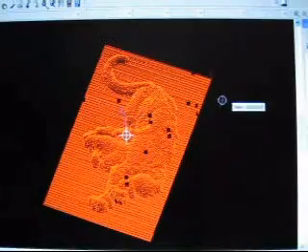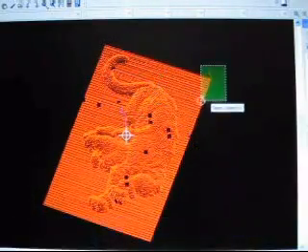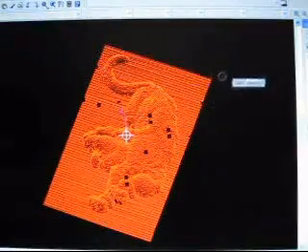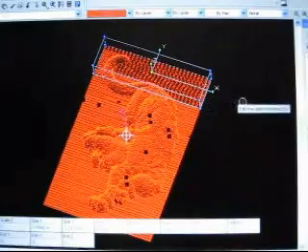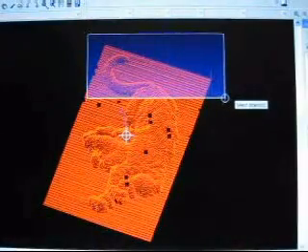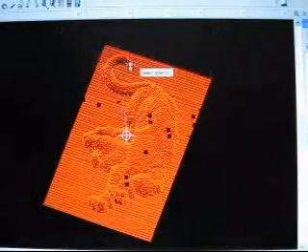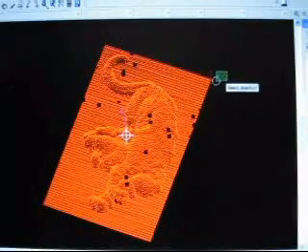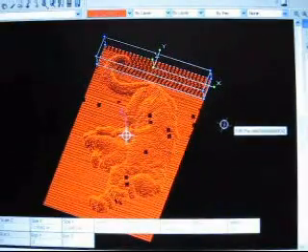If you drag to the left, you're going to select everything that the box touches. Okay, you see, I didn't draw a box around all of that, but it selected all of that, and that's exactly the feature that I like about this. If you drag it the other way, you got to go all the way around, so anything within the box then is selected, see? But this way, you only got to touch it, and it selects everything.